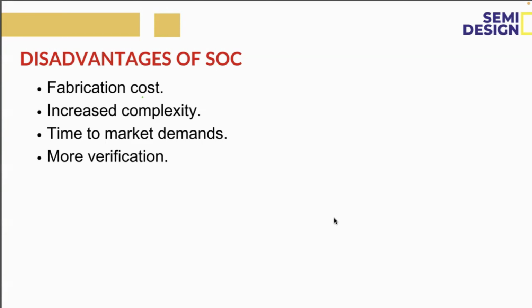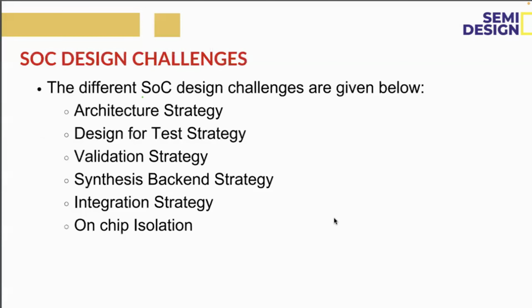And moreover, verification. SOC level verification is a very complex thing. It is not like IP level or small block level. SOC means both the CPU core and normal input output, all the blocks will be involved, right? So there will be connections with all blocks. But we won't verify at a low level, because IP verification means very low level. Their signals we won't take at SOC level. Whatever top signals are there, based on the top signals only we will verify. Okay, so that is the difference.